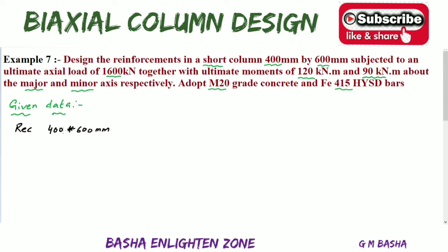Then, subjected to an ultimate axial load of 1600 kilonewton. Here it is given as ultimate, that means the factored load, 1600 kilonewton. Sometimes they give service loads directly, and there you have to consider 1.5 times that given load, then you will get the ultimate load. Here it is directly given in the question itself.